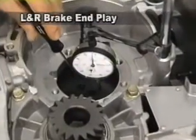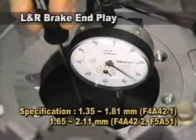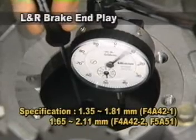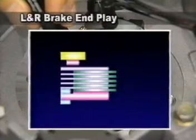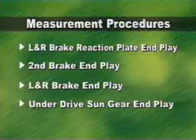Install the dial gauge and measure the in-play. If the measured value exceeds the specification, change the pressure plate of the low and reverse brake with one of the 8 different plates in thickness, in the same way as the second brake. To emphasize again, not a snap ring, but a pressure plate of the low and reverse brake should be changed.